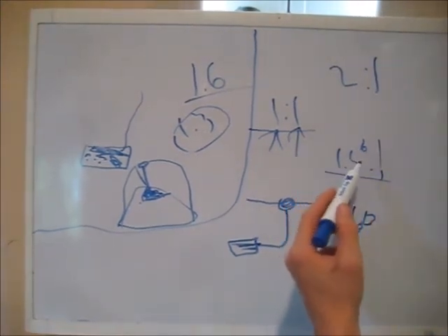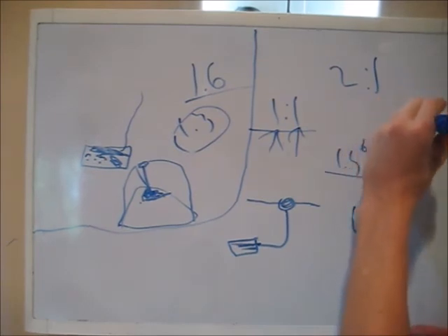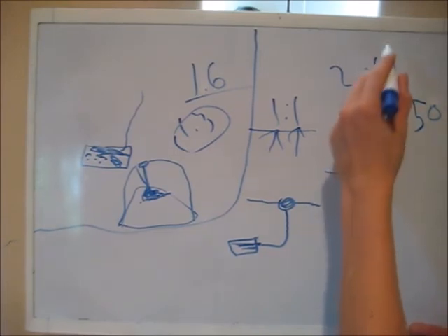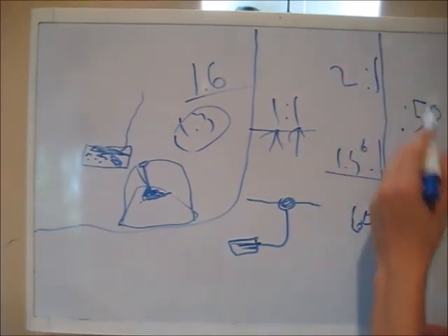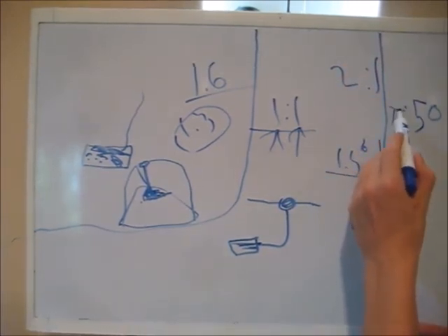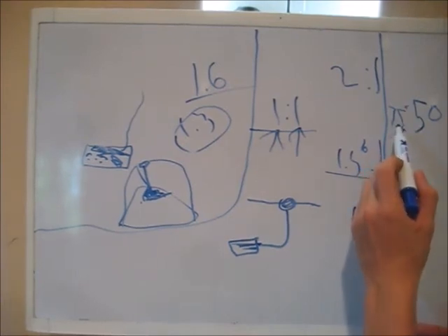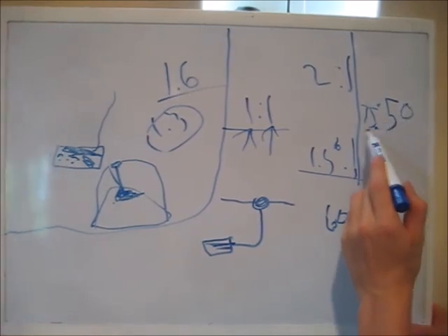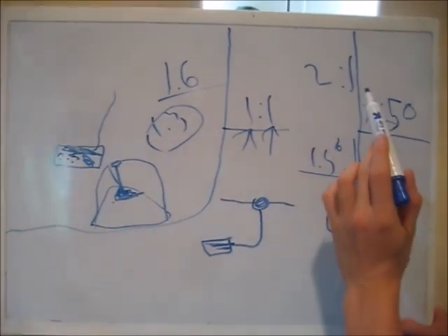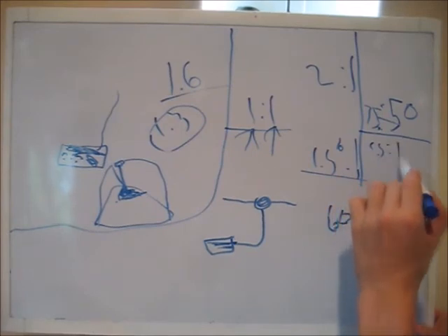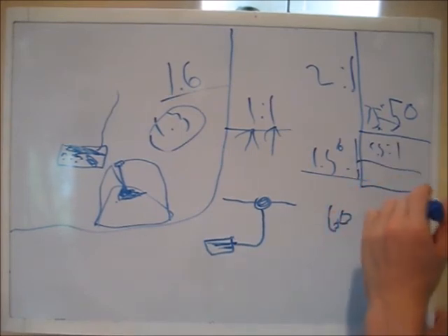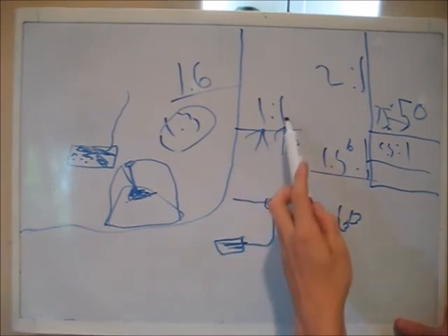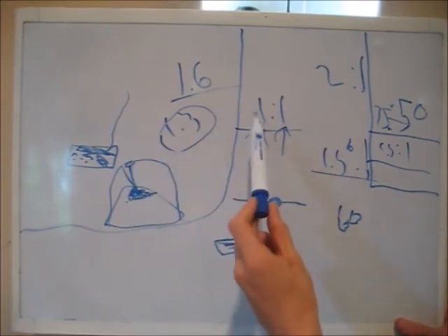So all you have to do is consider 50 ohms to whatever number. So your ohms is, you can consider at 50. Now 75 to 50 would be a 75 ohm feed line or antenna going into a 50 ohm coax. And you can obviously just divide this and reduce this to be 1.5 to 1. So you can easily reduce it. So all SWR is a ratio of 50 ohms to whatever the impedance of your antenna is.